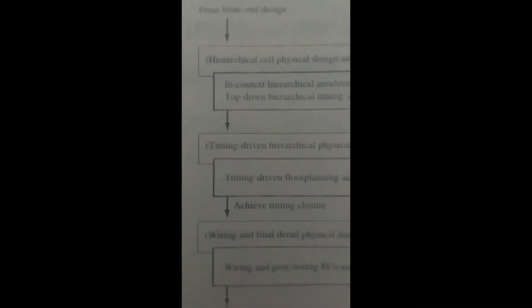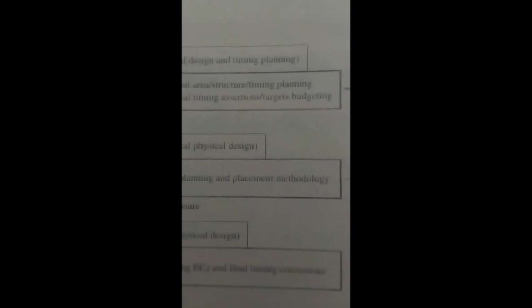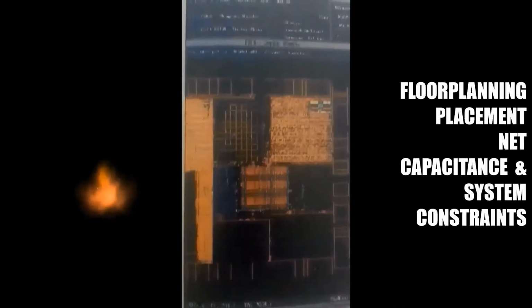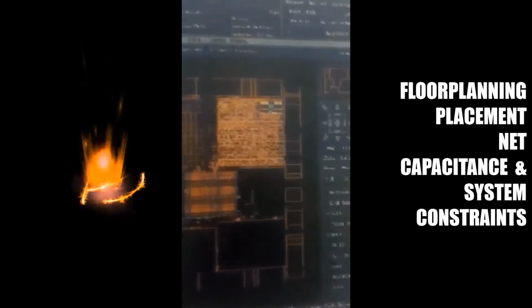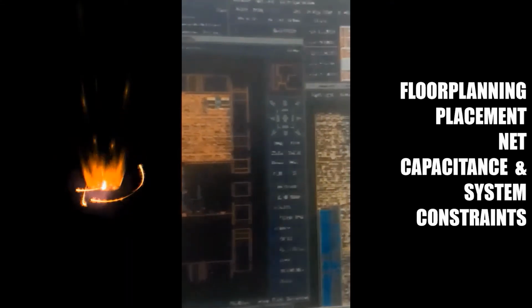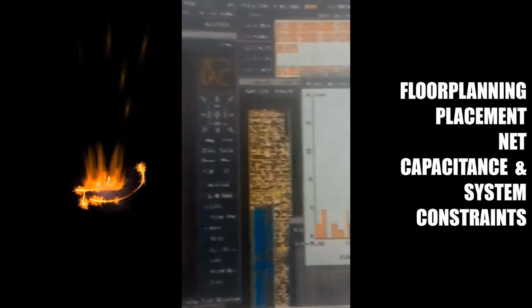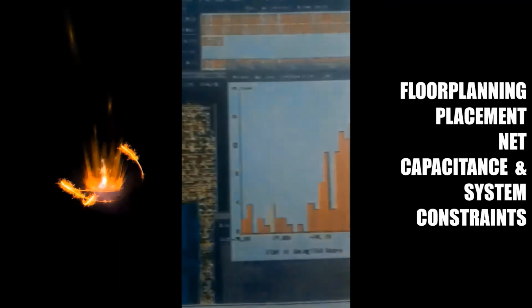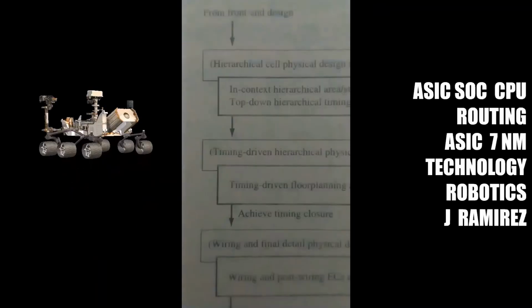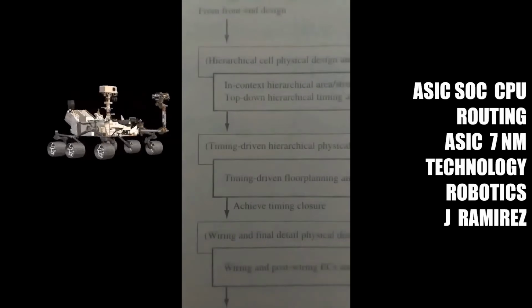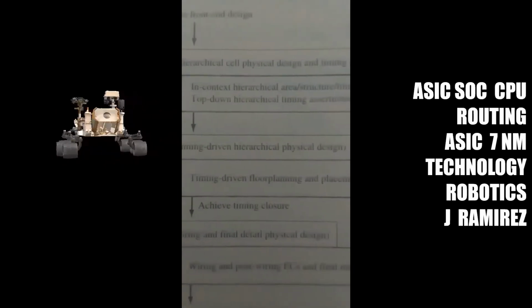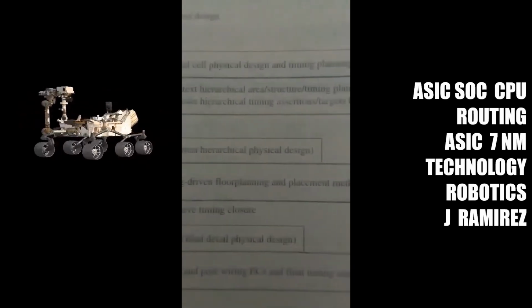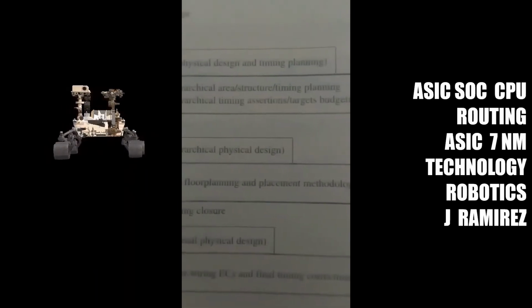They include pre-placement for planning, specification of circuits to be placed in adjacent locations, net capacitance and source to sink resistance constraints, and weights for the various components of the scoring function, including net length, congestion, and population balancing.